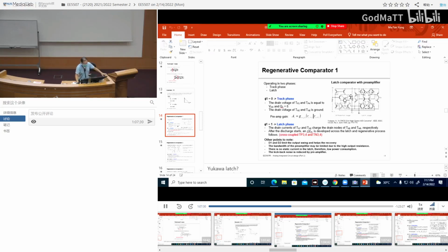So in this circuit, input is coming in here, output is here. If you finished part 1, you will learn that this is an amplifier stage. How do we know? We see the differential pair, the two inputs, the tail current source, and then the current mirror load. So this is a simple one-stage op-amp, which we use as a differential amplifier.